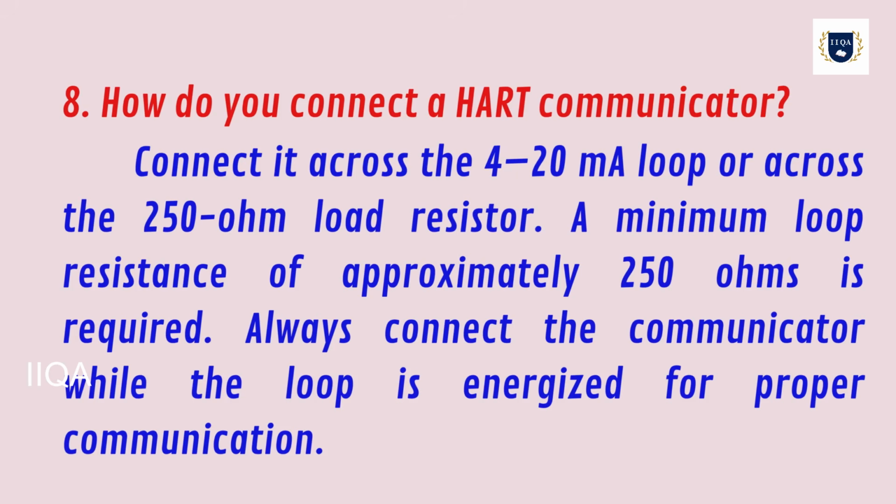How do you connect a HART communicator? Connect it across the 4 to 20 mA loop or across the 250 ohm load resistor. A minimum loop resistance of approximately 250 ohms is required. Always connect the communicator while the loop is energized for proper communication.